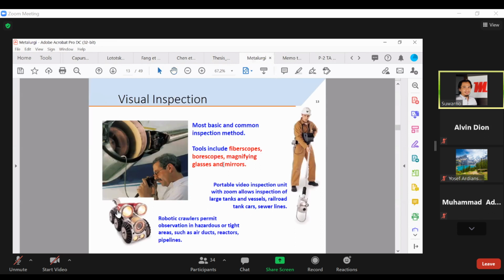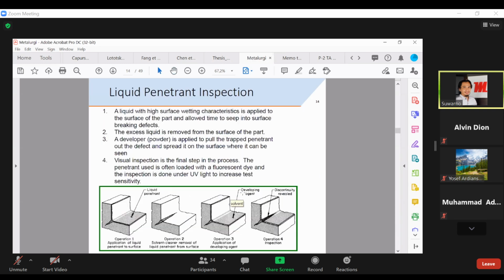So this kind of borescope, there you see already there is a real application of it, and then we also have liquid penetrants. There are also some applications that I have in my project, but I will not show it because the file is still somewhere. Basically, you have a crack, and the crack is on the surface. So liquid penetrant only works if you think that the crack is on the surface, because what is done is basically chemical.